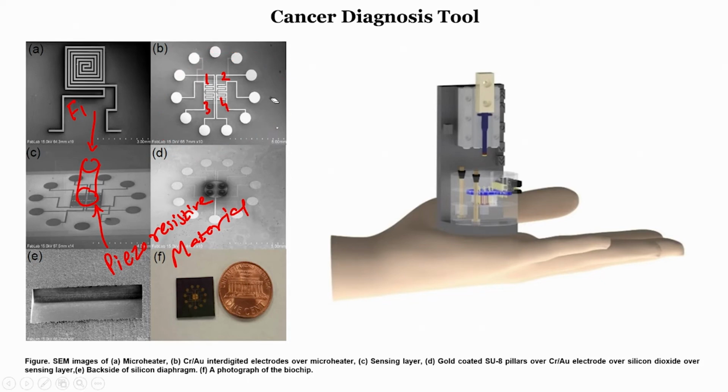There are 4 interdigital electrodes. So, I have 4 piezoresistors on which I have placed the tissue and am applying a known force. The piezoresistor will change the resistance based on the force that we have applied, but the amount of force reaching the piezoresistor depends on the elasticity of the tissue, is not it?